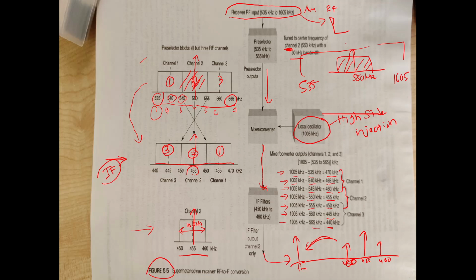So you see that the demodulation process does not happen directly. From the RF frequency band, we down convert into the intermediate frequency, then it will be passed through the demodulator. Within the IF section, it will select only a single channel, and this single channel will pass to the detector section, which will do the demodulation process to get the original output signal.